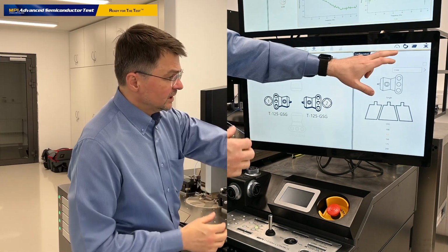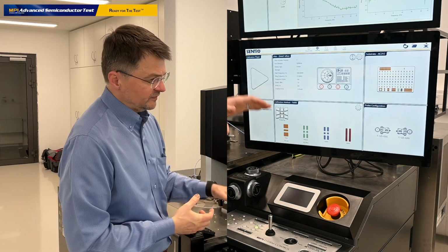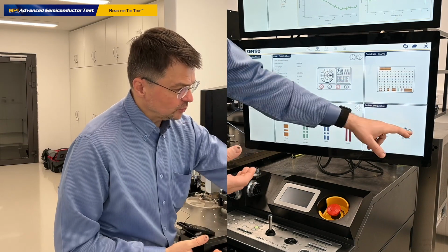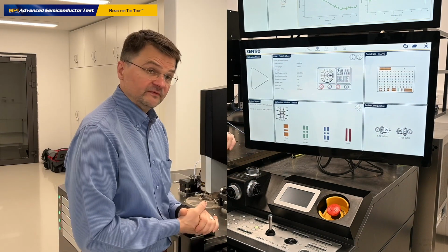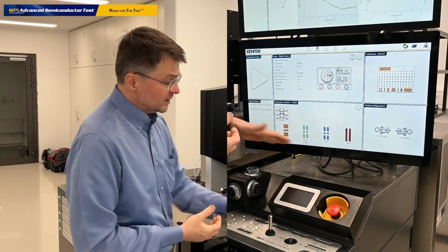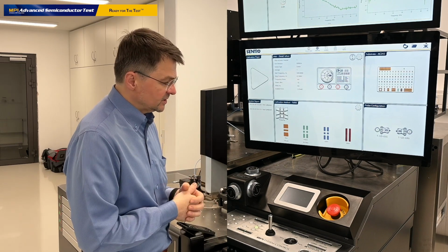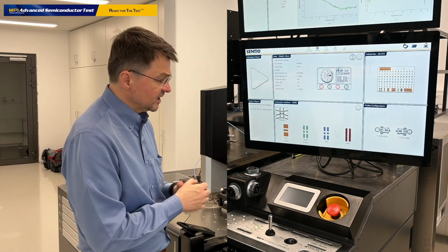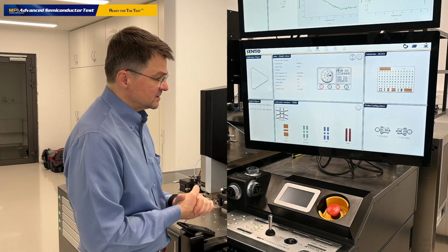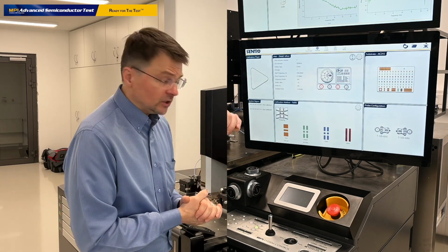Well, probes are configured. Let us go back to the dashboard of Calibria, and again, the snapshot of our current system configuration: AC2 V2 calibration substrate, Titan probes, port 1, port 2 connected to the vector network analyzer, and 125 micron pitch probes. We would like to use TMRR. This is a proprietary MPI calibration method to calibrate the system. The frequency range of our measurements will be up to 67 gigahertz. This is the maximum frequency range that the VNA can sweep to, and it looks like we are pretty ready to go.